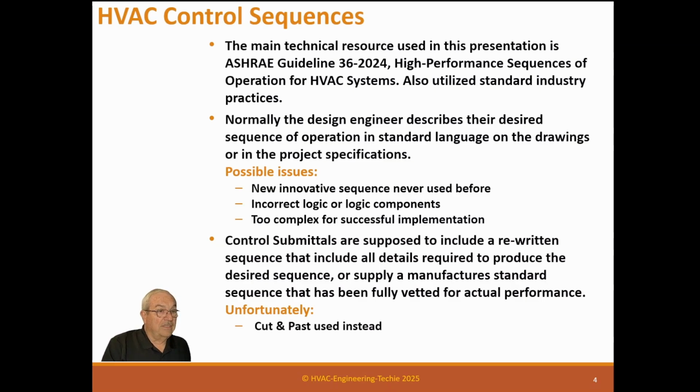Well, what happens, all of a sudden, as a commissioner, I'm sitting there with a sequence that has no entrance and exit points, it has no timers, it has no loop reset parameters, it has many, many things missing out of it that have to be added by the programmer. So we will know actually what he's programming. If we don't know what he's programming, we really don't know how to test it. And what that leads to many times is that the test fails. So please, we need to know the actual sequence the programmer is going to write, not the English language one the engineer's written. That's what it's supposed to do. Now let's create a sequence that makes it actually happen.